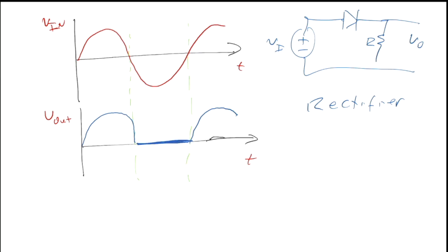We've got a rectifier circuit, a circuit that is blocking the reverse current, and you have a 0 output, and allowing the forward current to go through. And this will turn AC into DC, right? It'll change alternating current that swings from plus to minus to current that's only plus. Doesn't make it a stable current yet, but this is the first step to making a power supply. If we've got an AC current coming in off the wall, first thing we want to do is run it through a rectifier and turn it into a voltage that doesn't change anymore.